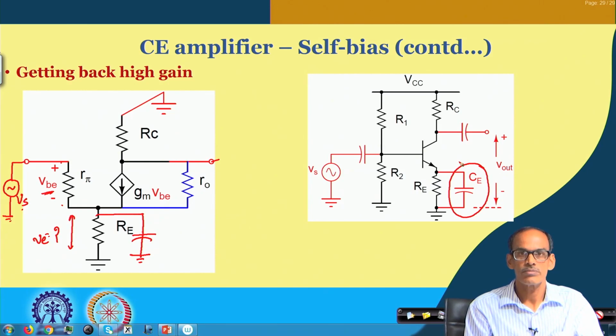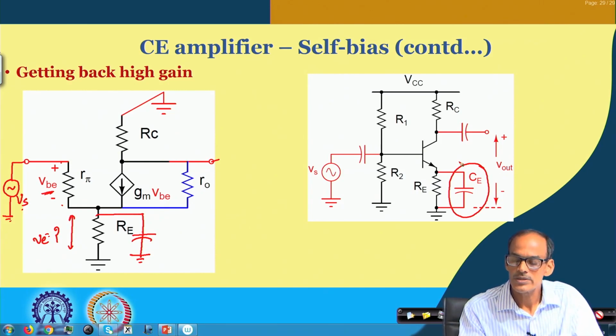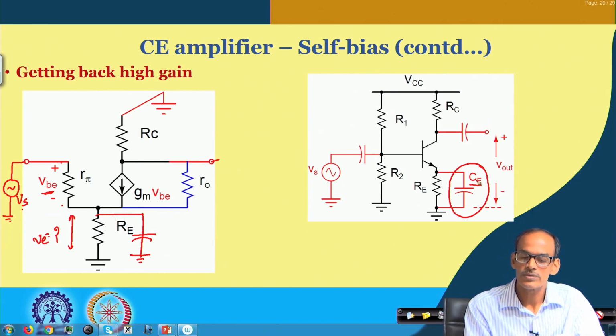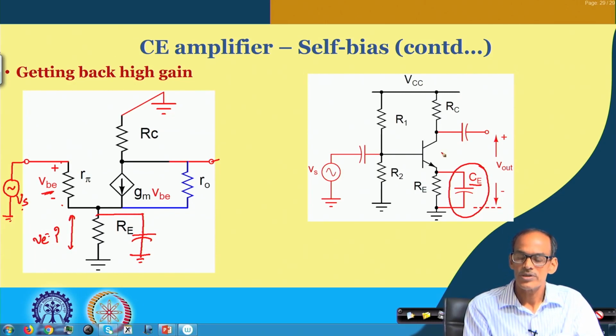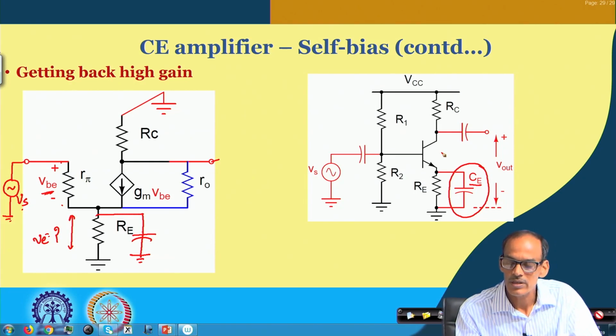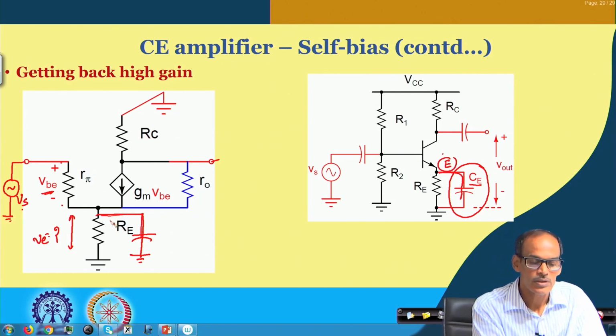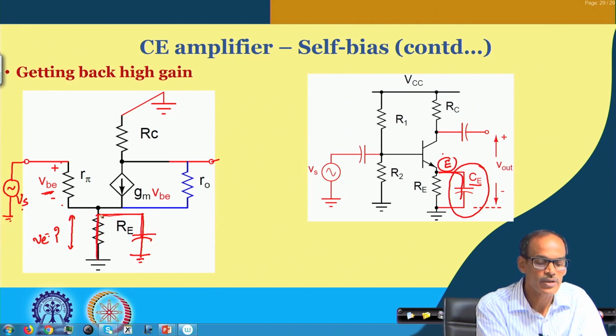So, this is the solution for getting the voltage gain back, and it does not disturb the circuit for the DC operating point, ensuring that the operating point of the circuit remains insensitive to beta variation, but for small signal or high frequency signal, this works as a short, connecting the emitter node to ground. As a result we can simply shunt it.